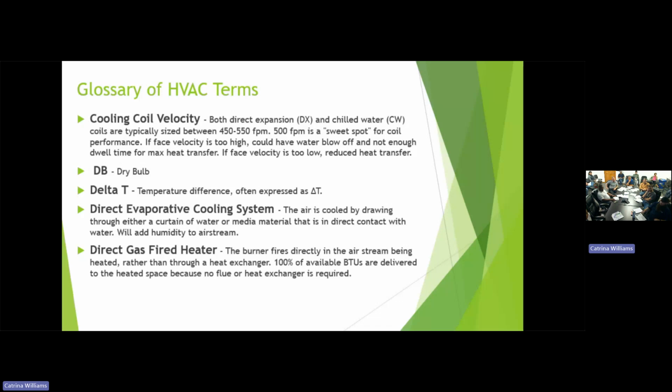If you have exhaust fans, let's say you're exhausting 20,000 CFM out by your welding booth, we're bringing in 20,000 CFM of fresh air. We don't want to just bring in cold untreated air, so we go through a direct fire burner to heat it up to, let's call it, neutral air. So you're not bringing a cold mass of air in here. They're very efficient with that.